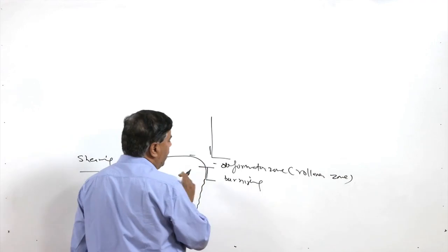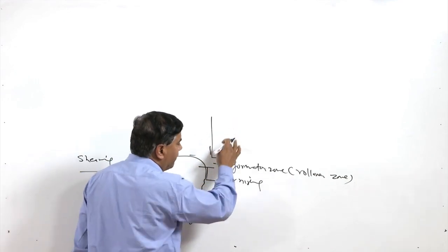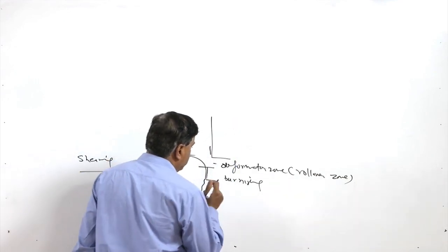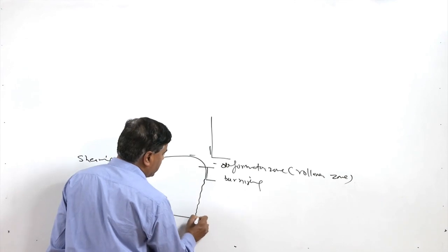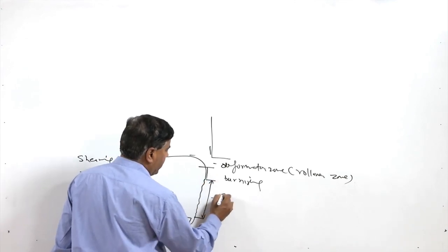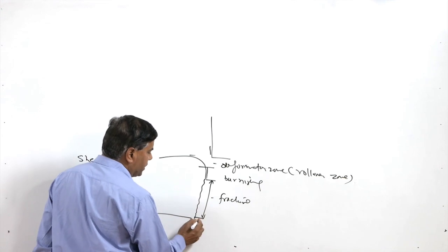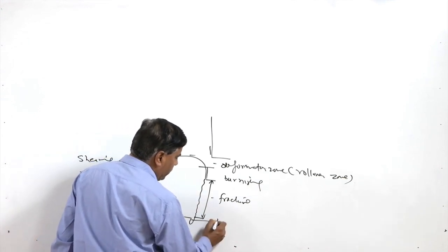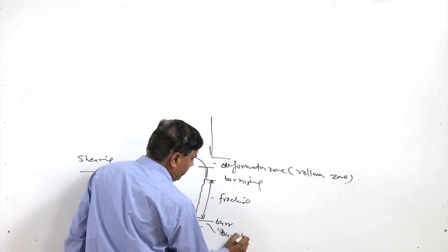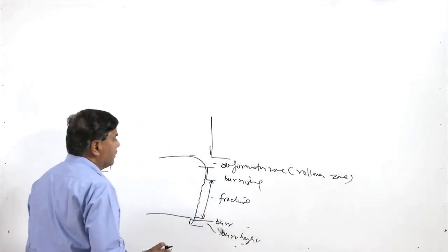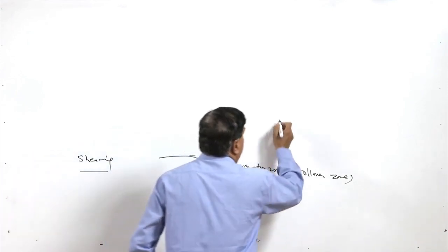The burnishing zone is formed by rubbing of the sheet metal which has been penetrated by the punch in the course of its movement. Then when the cracks start propagating from both sides, they result in the fracture surface. So, this region will be experiencing the fracture, and due to the deformation of the material beyond its lower edge, one burr is formed. This is called the burr height.